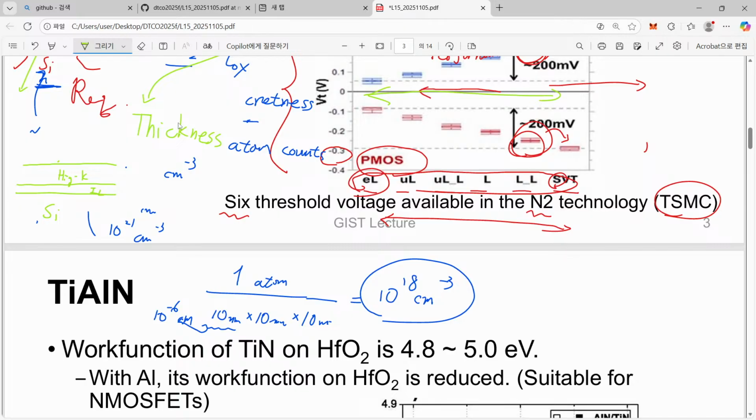So right now we are talking about FinFET. If we just visualize its cross section, it looks like this. Of course here we have an STI and STI, but this one is electrically not active. With this shape, this height is currently assumed to be 32 nanometer, but it is much higher in our advanced FinFET node.